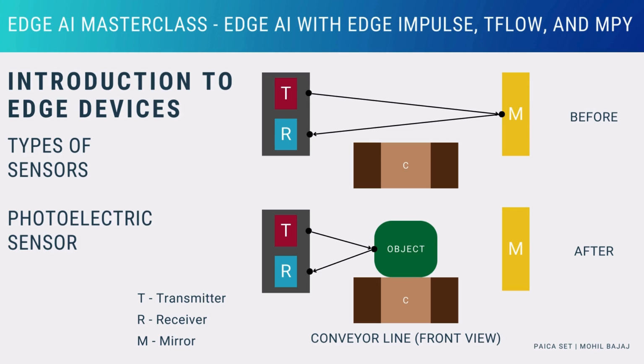When an object comes between the mirror and the sensor, the missing or low-intensity signal is detected and information is sent back to the controller. They have higher accuracies than the diffuse sensor and are easier to install than the through-beam sensor, and thus have varied applications. They are especially useful in applications where the objects are fast-moving.